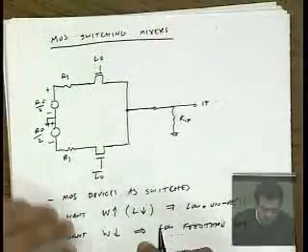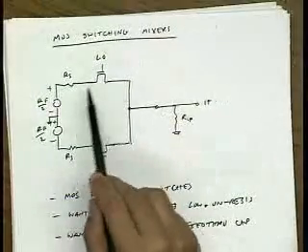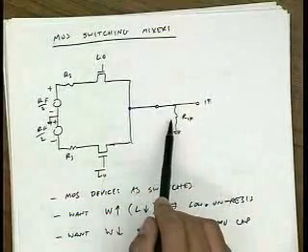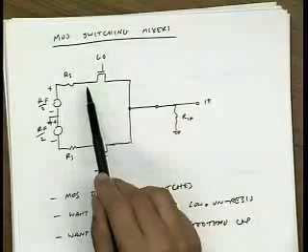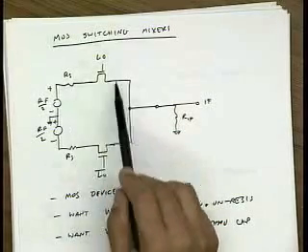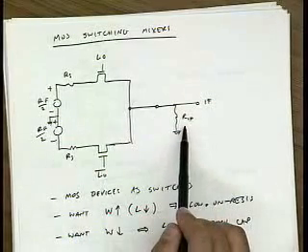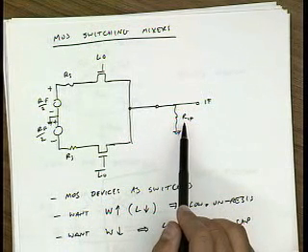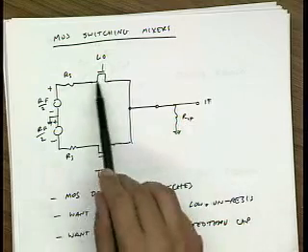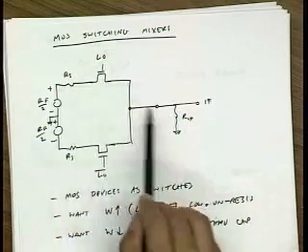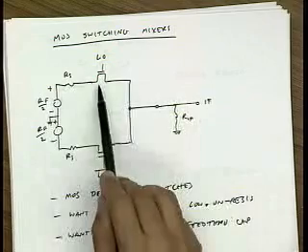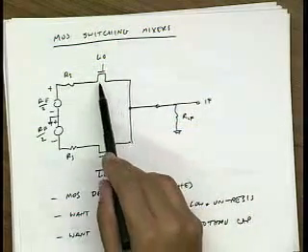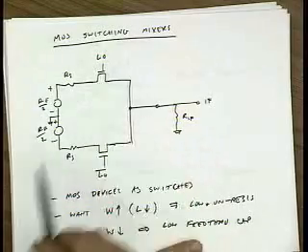If we come back here, if this were no resistance, I could design a matching network so that this source resistance is matched to this resistor here, right? On the other hand, any resistance I put in here is extra power lost that's not getting to my load, right? So you could, but there's going to be some current flowing through here, right? And no matter how you look at it, the power loss is I squared R, 1/2 I squared R for a sinusoidal signal. So you want to minimize the power you lose in that switch.